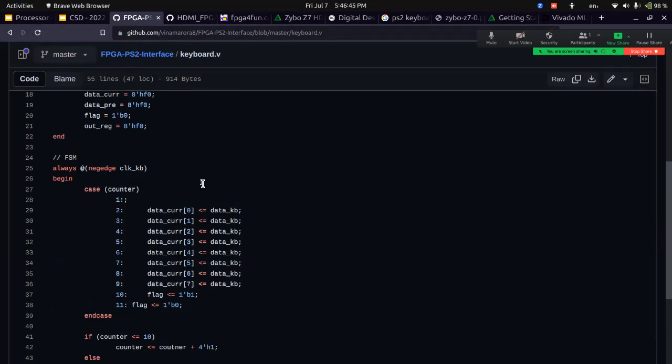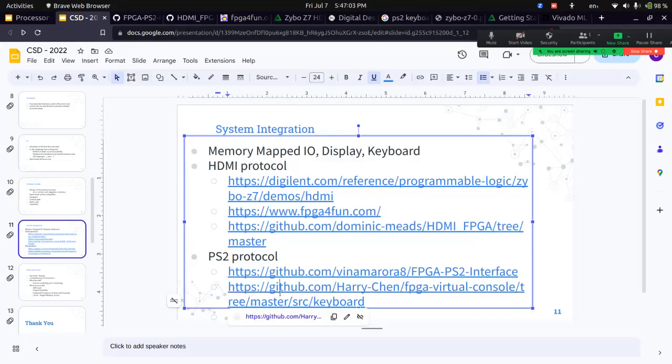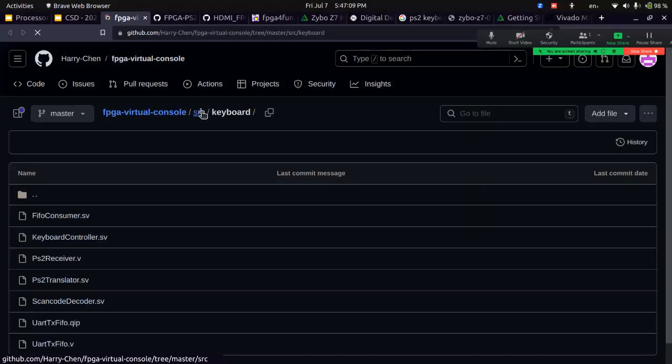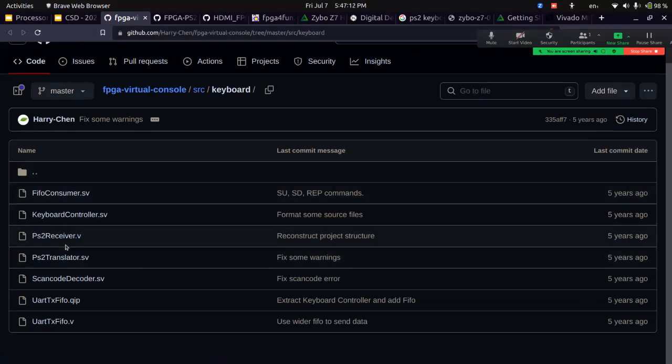We studied how the PS2 protocol works. So I think 10 bits, I think there are 10 clock cycles. 8 bits is the ASCII value, not ASCII value, Unicode value, not even Unicode, byte code. There's some name. So it's not ASCII value. When you press a key on the keyboard, we thought it was ASCII, but it's not ASCII. The data that you get is something called a scan code.